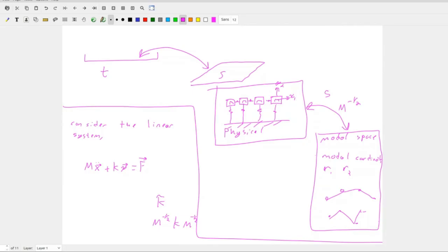So you're going to come down into modal space where you can actually gather data and then bring it back out. But you can't bring it all out. You can only really bring out the first 10 modes, let's just say 10. How do you know which ones to truncate? After 10, you just can't measure them. They get really hard to measure, and then they fall into the noise. Also, you have to have an understanding of how the system responds, because you have to know where to put your accelerometers. That makes sense?